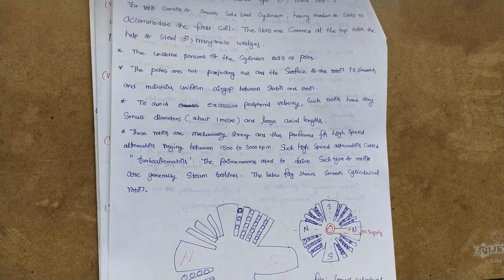Assume a winding with poles N and S. The coil span is short by an angle known as the chording angle. One coil side is placed in the north pole, and the other coil side is not placed at the full pitch position. It is less by some angle, that is known as the chording angle. The other coil side is placed leaving one slot, and that is short pitch winding. The chording angle is epsilon, and the coil span is 180 minus epsilon. The distance between north pole and south pole is 180 degrees. What is the coil span here? 180 minus epsilon. That is the difference between full pitch and short pitch winding.